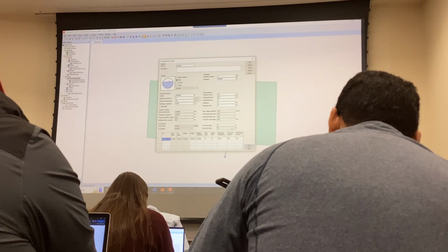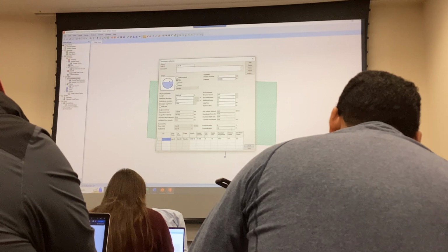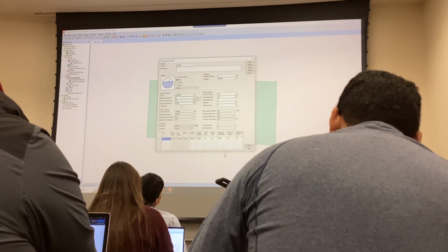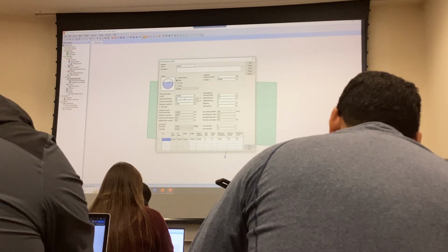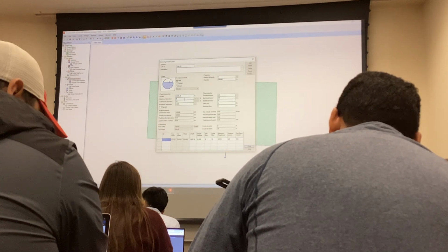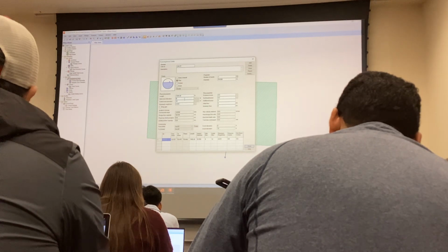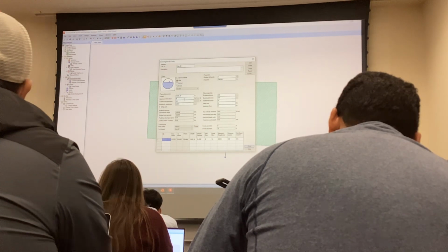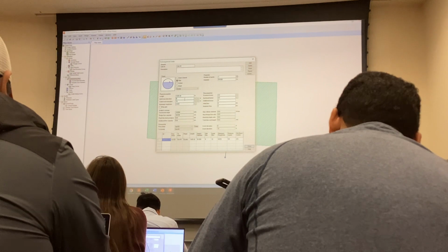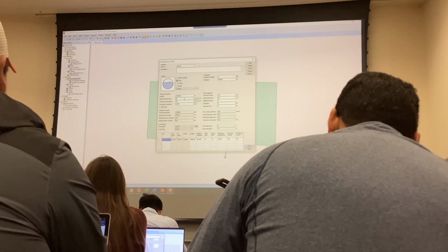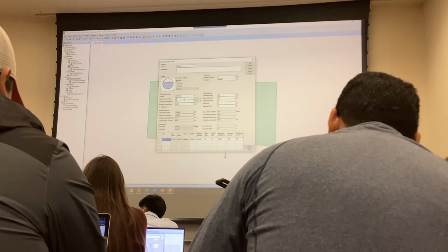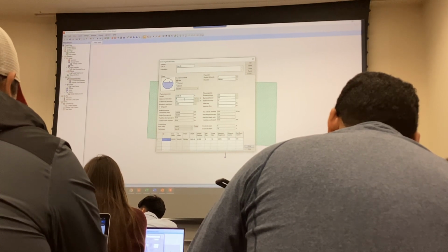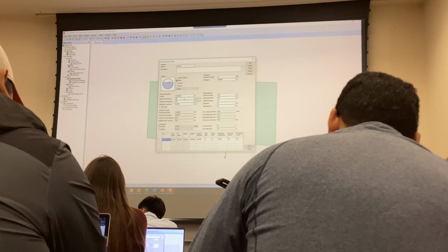Why? Because it's not going to pipe anywhere. It's just going to be stuck in the ground, right? So you need to make sure that your invert elevation is inside the range: you specified this as 10 feet elevation, and this is 16 feet, right? Whatever you do, you need to make sure that your pipe stays within that range for the program to understand that you're piping it through gravity flow into your detention basin. Otherwise, it's going to be an adverse flow going uphill.